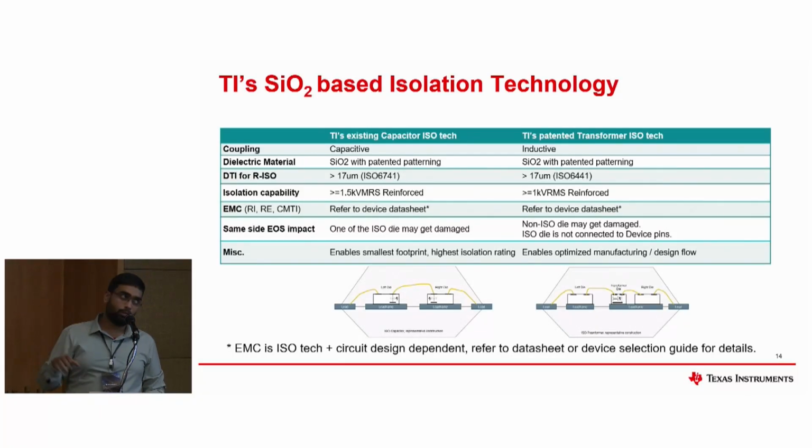In both scenarios, a high frequency component gets injected from TX to RX to be read by the RX. A lot of the signal strength is lost through the two series caps to be detected by the receiver side die. Whereas here, the coupling factor improves by 10 times, and this requires less power on the left and right side die to be operational in day-to-day applications.